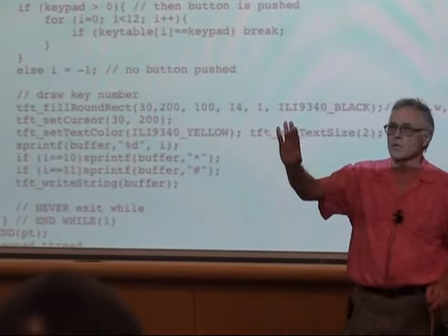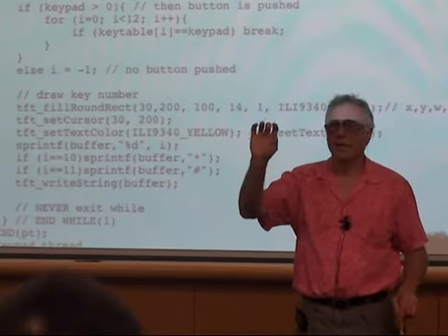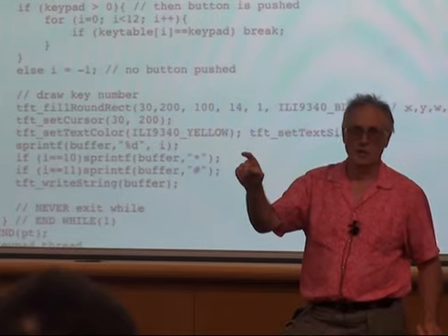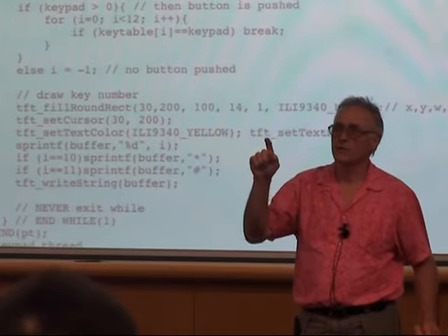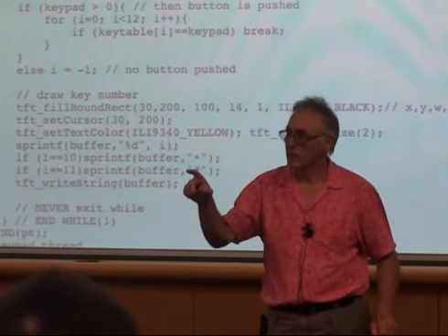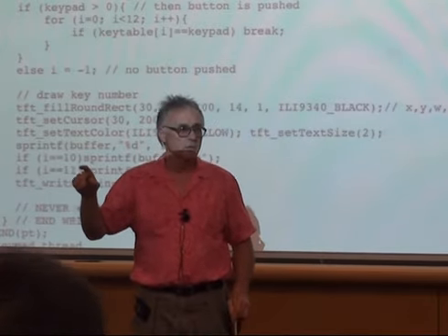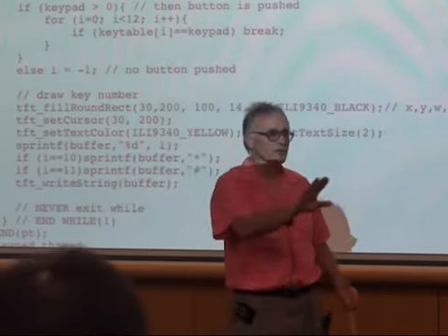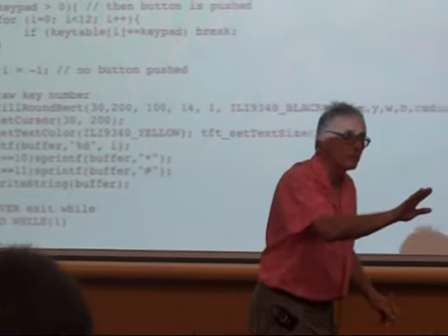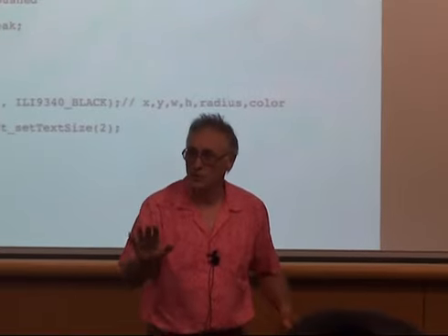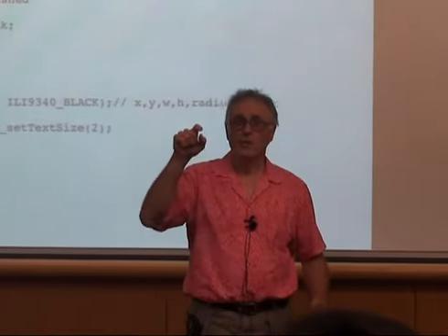So the scan code is going to return a possible digit to a state machine, which is then going to determine whether at a higher level the push is valid or not. So at the low level, first of all, we have to make sure we have a valid button push. Now the next step is to make sure we have a stable button push, that when the user pushes it, it isn't still bouncing.